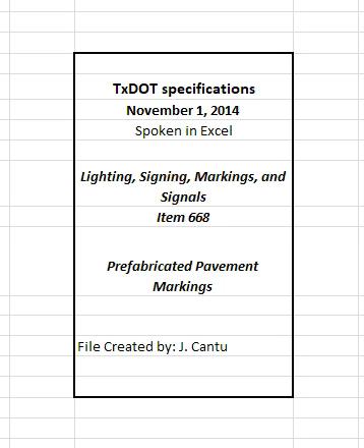3.2.1 Moisture. Apply material to pavement that is completely dry. Pavement will be considered dry if, on a sunny day after 15 minutes, no condensation occurs on the underside of a 1 square foot piece of clear plastic that has been placed on the pavement and weighted on the edges.